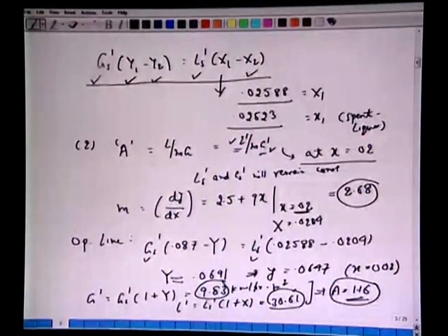So, here also we can conclude from this example that the absorption factor changes along the absorption column. Why? Because even if we have a linear curve, the slope m may be constant. Here of course it varies, but in those cases where the slope changes, it is possible that L prime over G prime or L over G will change along the length, because liquid flow rate changes, gaseous flow rate changes, so there is mass transfer, and not necessarily will the L by G ratios remain the same.